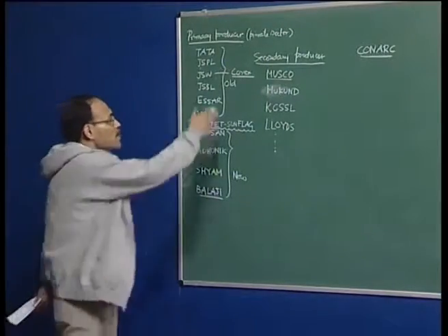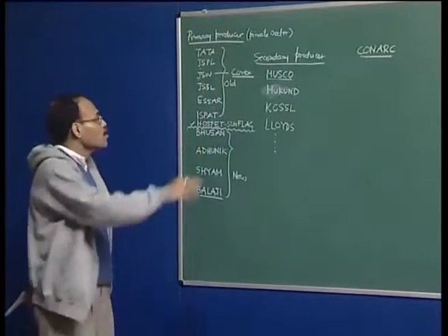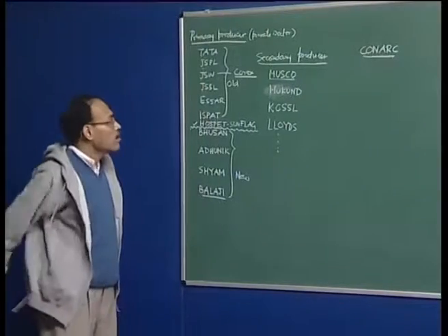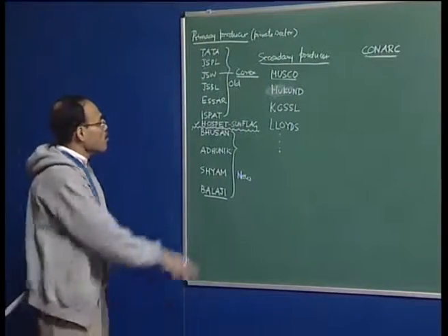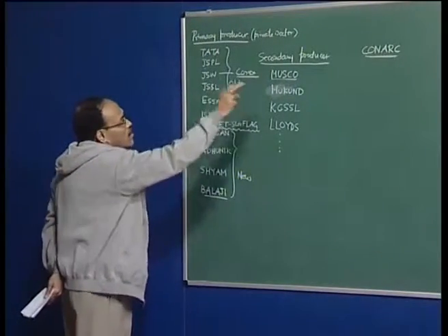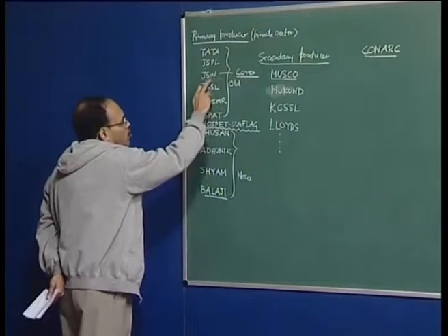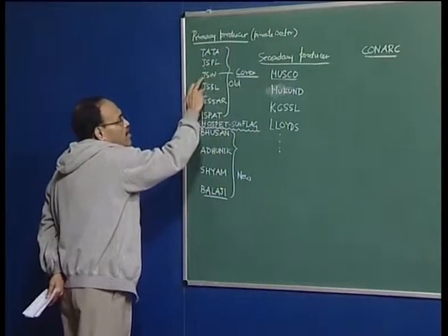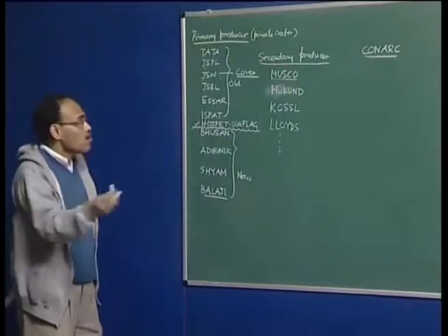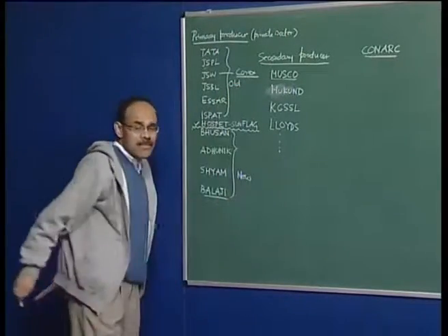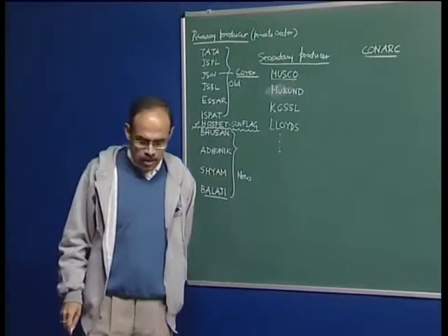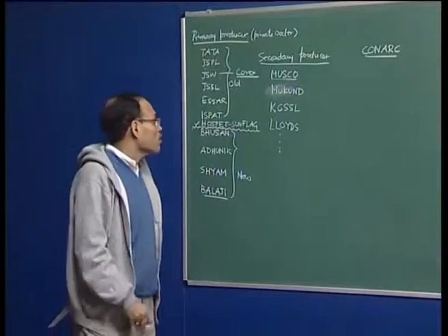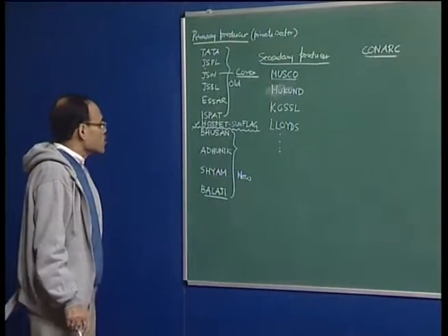This is a direct smelting reduction process. If you know, this is the only plant in India which has these facilities. So Ispat has a Corex process. Corex does not. JSW has both blast furnaces as well as Corex. We also know that the Corex process produces high calorific value gas, which can be converted into power also.